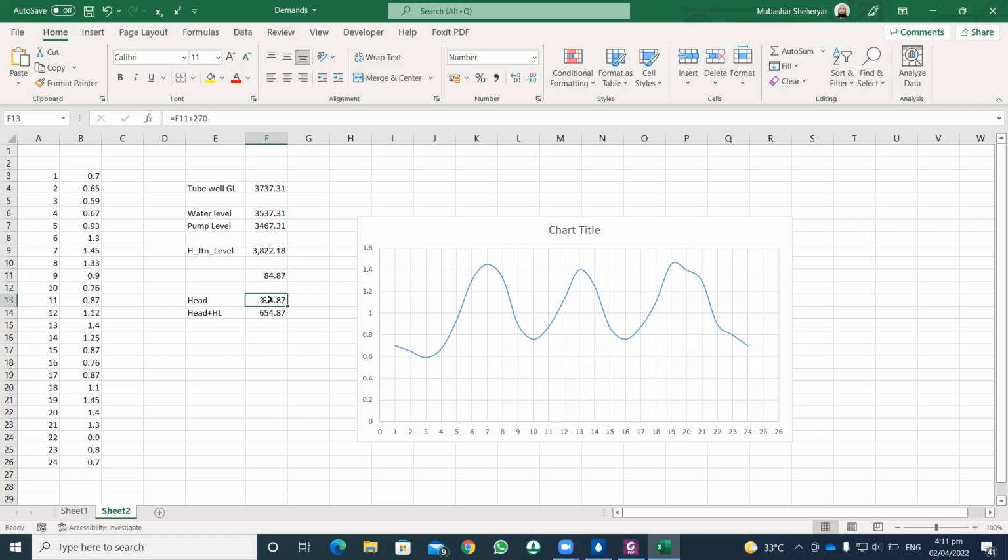So when we supply water to the water supply network, there are minor losses, head losses. So I am also considering these head loss parameters. I am assuming the total head of 354 and then adding the head losses to this. So basically, this is to calculate the head required for a pump, that is, how much head of pump will be required.